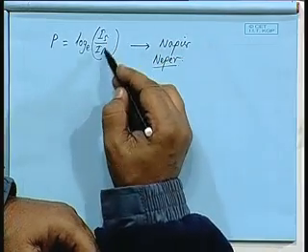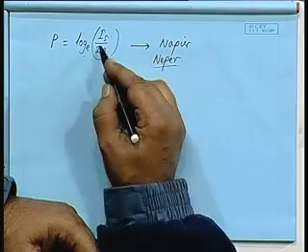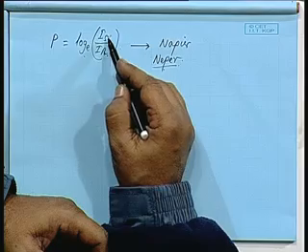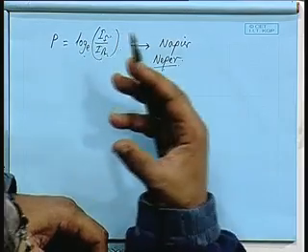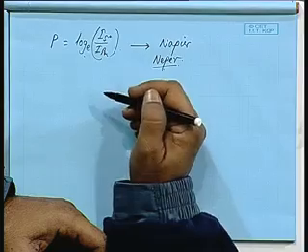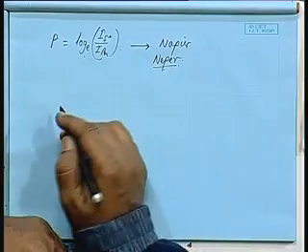Mind you, this is a dimensionless quantity, it is just a logarithmic quantity. It refers to the current gain or current loss, you can say, how current propagates, how it gets diminished or reflected by this ratio when the network is terminated by the characteristic impedance.